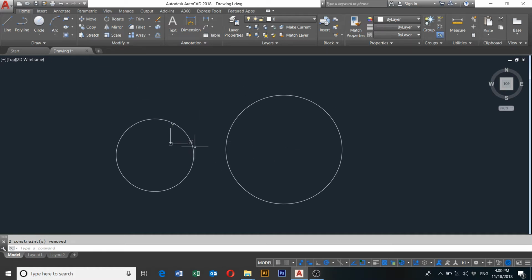Now I want to move either this circle here or this one here. The rationale behind it is just to move objects around in AutoCAD. Let's assume I want to move this one to here. I want to make sure the two circles are concentric. How do I do this? You just select the object, which is a circle in this case, then you click on move. When you click on move, before you start moving, AutoCAD will ask you to specify the base point. The base point is actually a point of reference, something that you can easily relate to whenever you are moving the object.